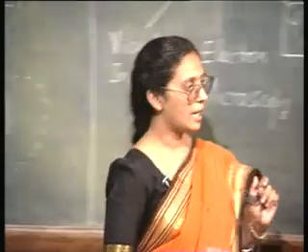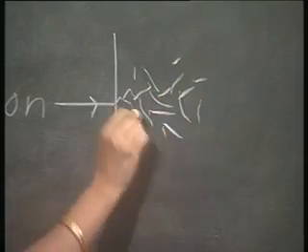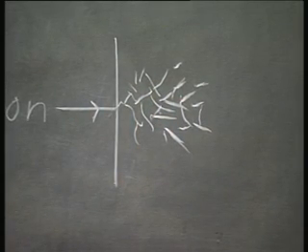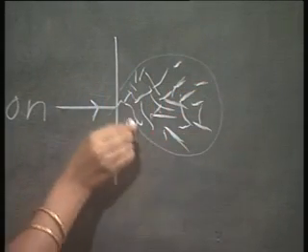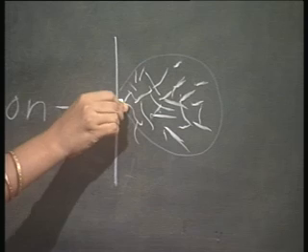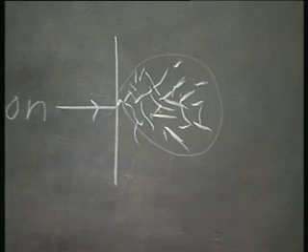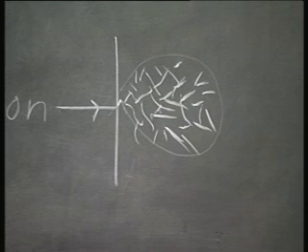Agreed? So, what I will have is actually a horribly damaged region, but within a small volume. At every point there is a collision, and that collision is sufficient. The lattice atom has obtained sufficient energy so as to cause further damage. So, it is full of damages, that region is full of damages, but within a smaller volume.